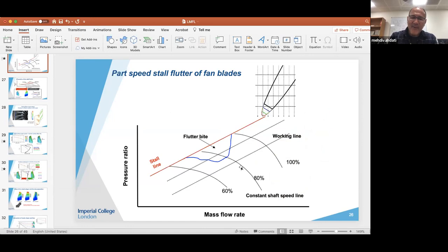They can recover from it, because usually you can see some signals of vibration beforehand, so you are ready to open the downstream throttle during a test. Unthrottling and moving the blade to a lower working line usually gets rid of it. I'm not aware of hysteresis, really.